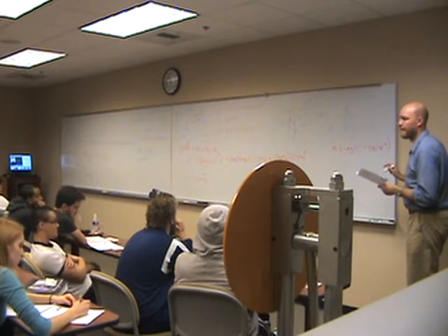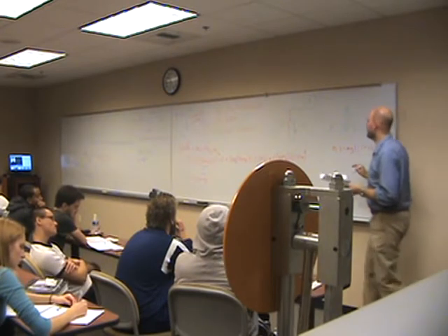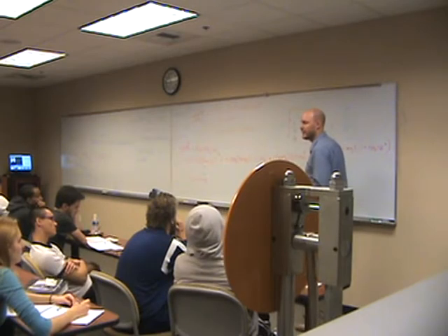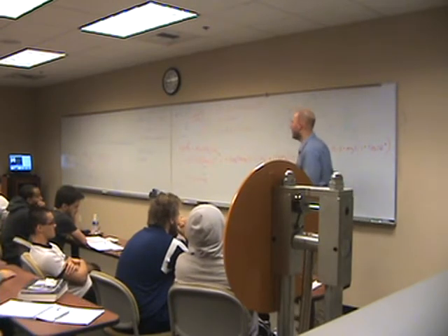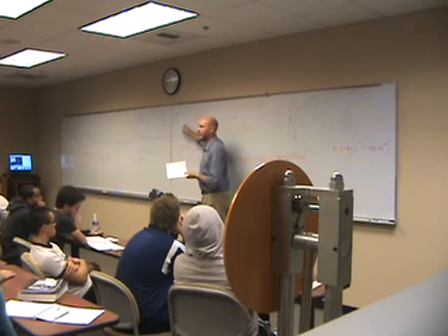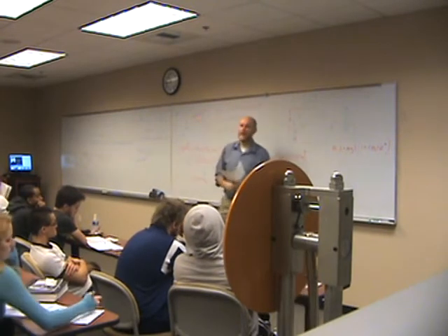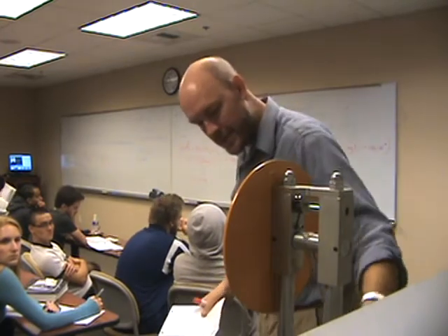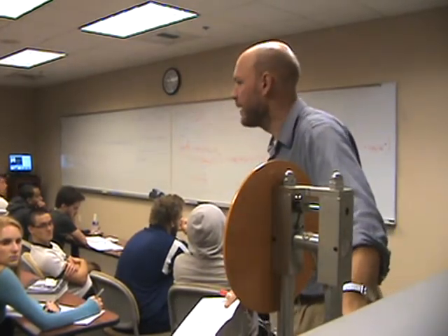Okay. Is L the total length? L is the length to the CG. Oh, to the center of gravity. Yeah, mgh, remember, h is to the center of gravity. Now here we don't have a simple rod, we have a complicated structure. So the center of gravity is probably going to be maybe right here, I don't know.